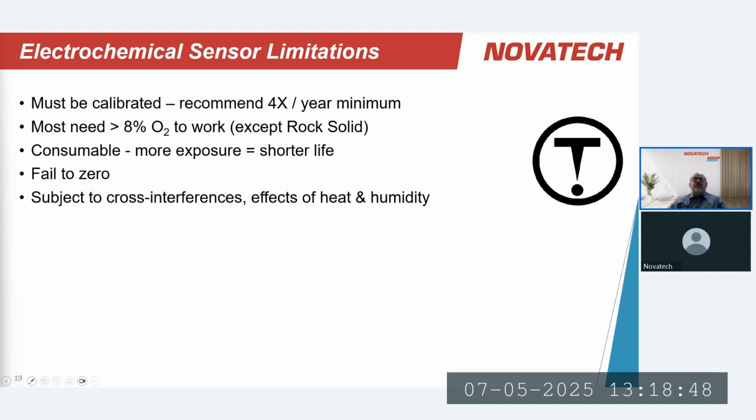You may be looking for a hazard that exists perhaps in a storage room or a storage locker or in a sump or something of that nature. And another gas may come along that you're not searching for, not detecting, that could suppress the oxygen in that environment. And now your sensor is no longer functional. So it's something to absolutely take into consideration.